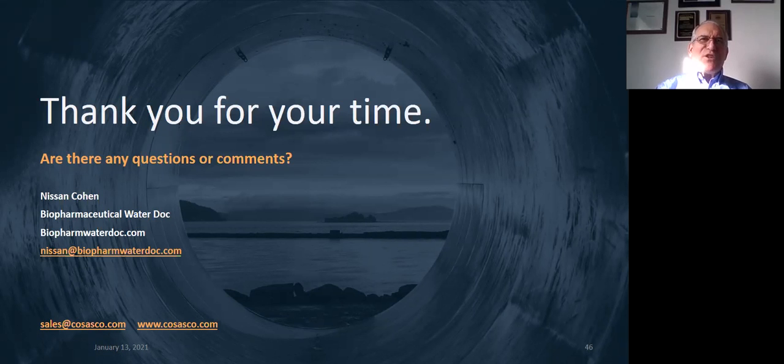It's more the interaction of the water and the chemistry with the piping and the vessels, which causes the hematite, again, the hematite and the magnetite. Don't forget, we do not do derouging for particulates. We do derouging in order to get rid of the corrosion that's actually on the vessels and the piping. Particulates can be removed if it's a problem by filtration, and that's the easiest way to get rid of them.